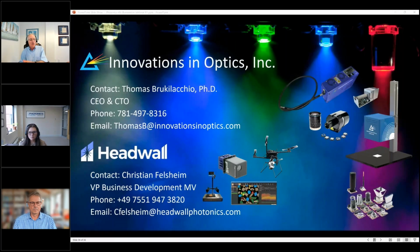So that's why you want to bring the angle away from the normal to direct the specular light. So if you're looking at things like poultry or meats and so forth, they have a lot of water content, and so you're going to get pretty high specular reflections. So systems like that, you want to redirect that specular reflection away from the camera.